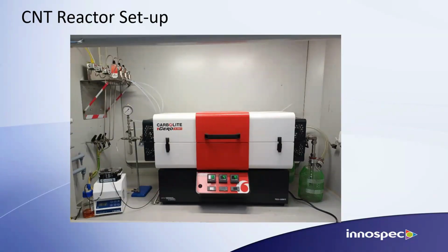But in this image, the furnace is set up for direct injection. The metallocene is shown on the left of the image, and it's been dissolved in toluene, the liquid carbon source. And this is injected at a controlled rate into the first preheat zone of the furnace. If we were using solid-state catalyst delivery, the crucible containing the metallocene would be placed in this first preheat zone of the furnace. But in both catalyst delivery systems, the metallocene and the carbon source vaporise and thermally decompose in this zone before the carrier gas transports the resulting species into the higher temperature growth zones 2 and 3, where the carbon nanotube formation occurs. Any off gases that are produced pass into the catchpot and a bubbler before being vented.